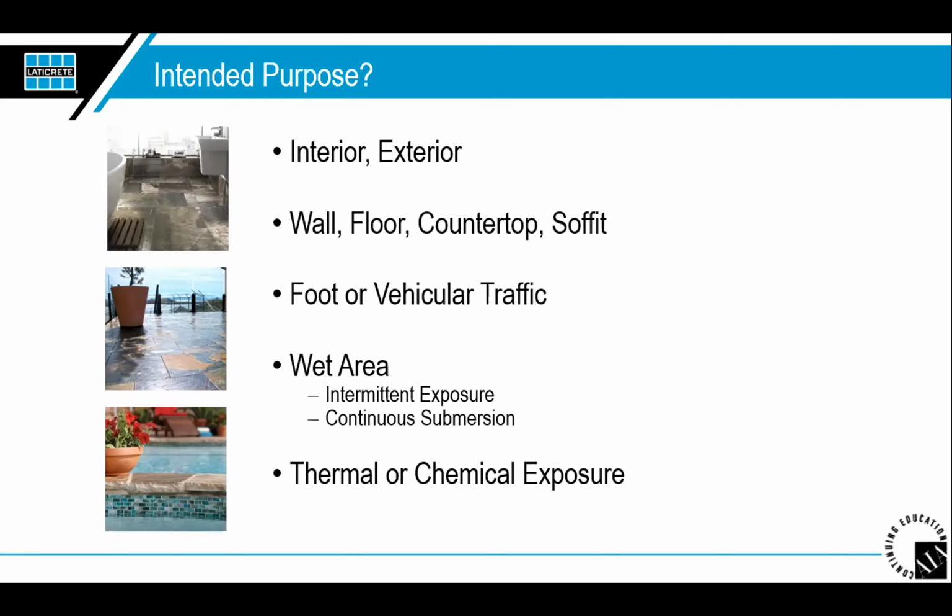A big question is: is it interior or exterior? Knowing if the installation is interior or exterior is vitally important. You have freeze-thaw conditions, thermal expansion and contraction, traffic, and moisture that can and will affect the tile installation as a whole. All types of applications are affected differently by a variety of stresses and movements. Vehicular and foot traffic put different types of stresses on an installation, and the tile and setting materials must be able to handle that load.